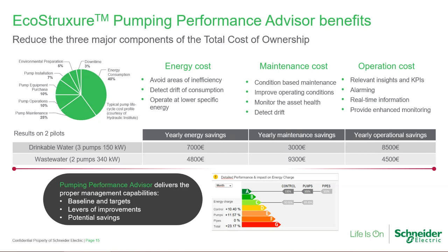All of this, as I've talked about, is agnostic. The choice in this case predominantly is driving down the VSD route, which is obviously the most efficient route when you come to energy efficiency of big pumps. But with the knowledge that utilizing something like TeSys Island, which I spoke about, which is a digital DOL, it gives you the ability to also start tapping into those digital advances, even on DOL starters.